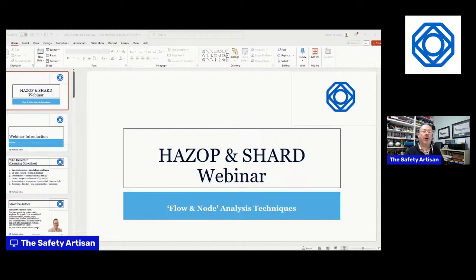And that will help you understand the system. As we'll see, it's very important for the moderator, the leader, to understand the system. And also, of course, if you've done a coarse HAZOP or a hazard ID HAZOP to start with, that'll inform you for the full HAZOP.